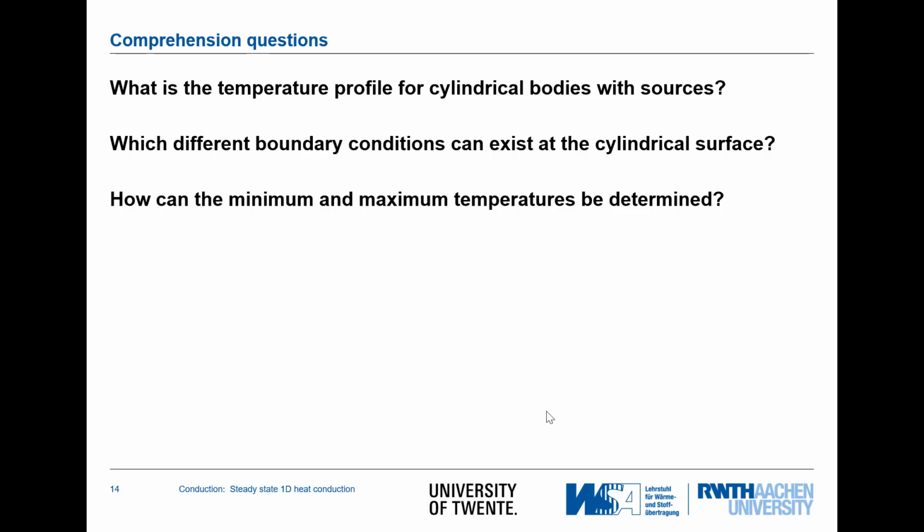Now, here I would like to also discuss what happens if we prescribe a heat flux on the body surface. Is this possible? It's the first question. And of course it's not, because the heat flux is directly known due to the integral of the volumetric heat flux times the volume, and as such we will not yield any new information if we prescribe a heat flux. If the heat flux is different, we violate the steady state condition, and if the heat flux is equal to that value, we don't have another condition for the solution of the equation.